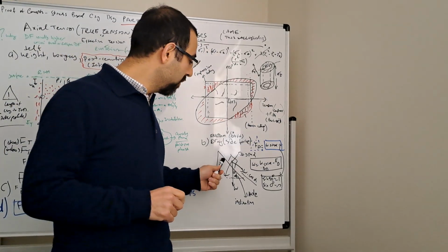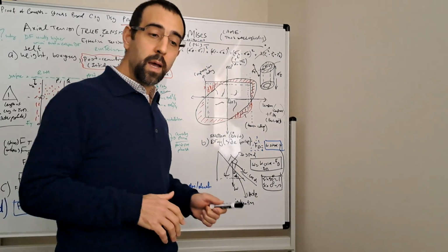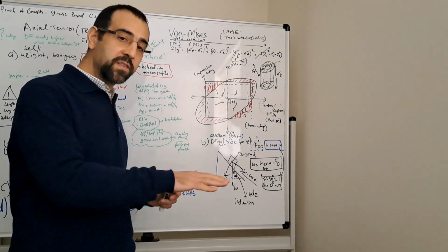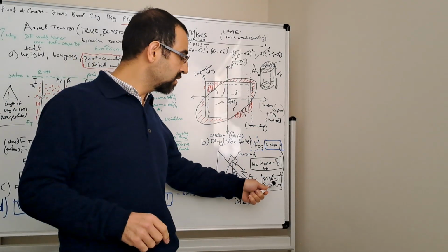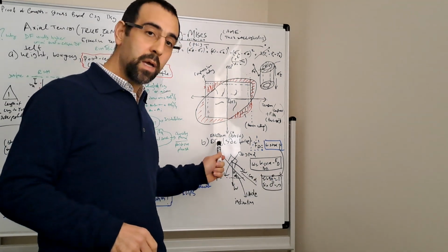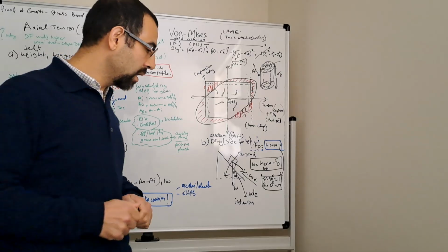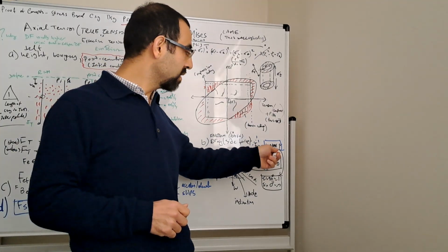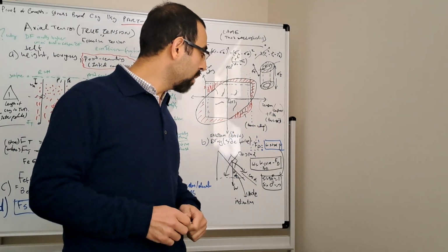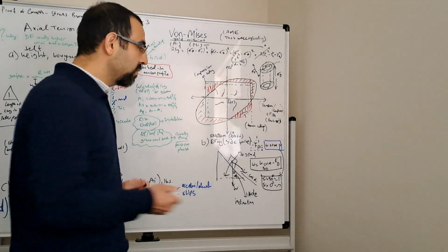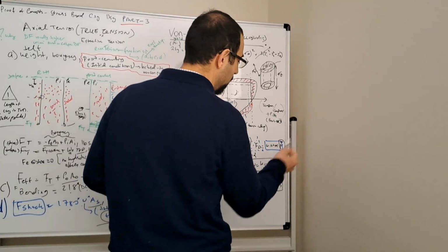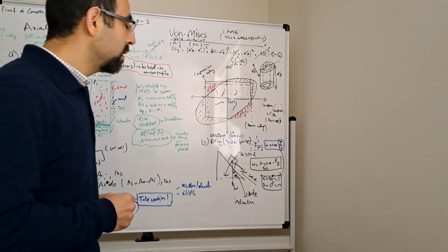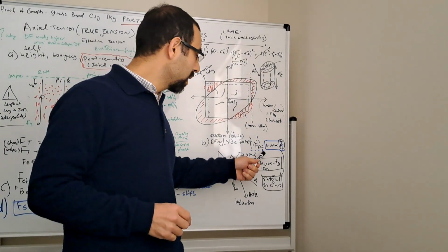However, in a deviated hole, let's take the most extreme case of a horizontal well. So that's 90 degrees, right? What is sine 90? It is 1, which means in the horizontal section my friction-related side force will be the highest, because weight times sine alpha is the weight, and then you multiply that by the friction factor. So what is that friction factor? It is a case and open hole factor. They will be separate, different friction factors, but that's how you come up with your drag force.